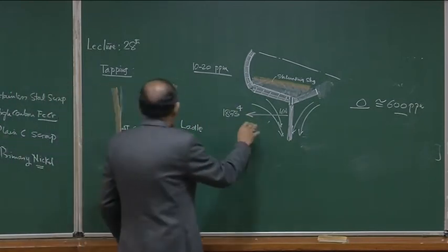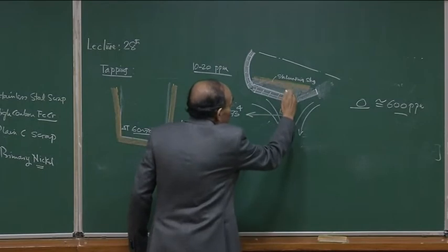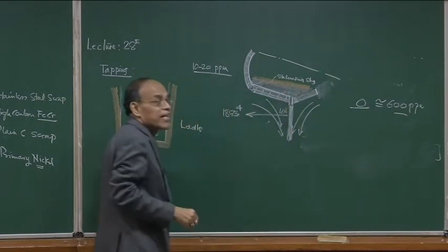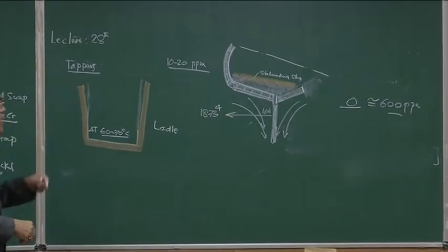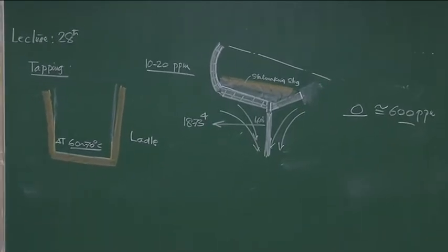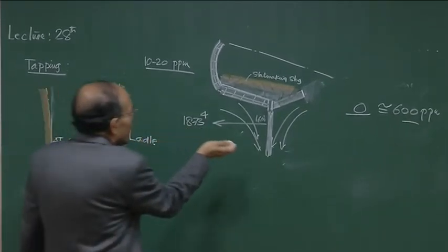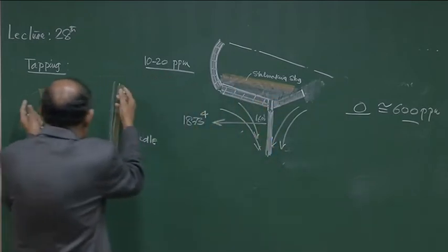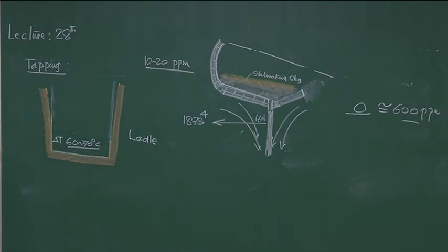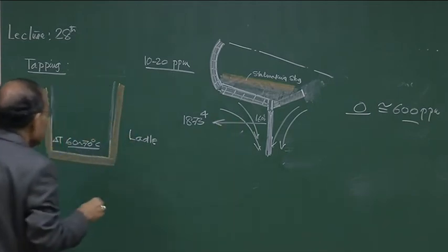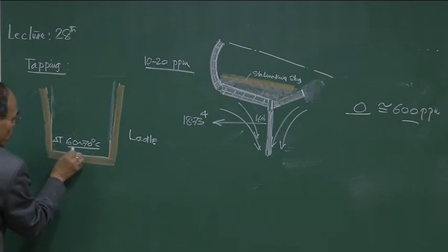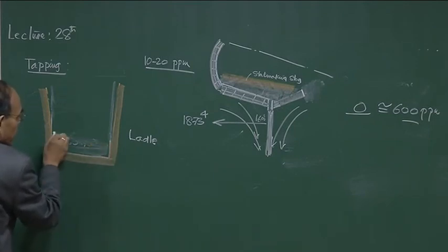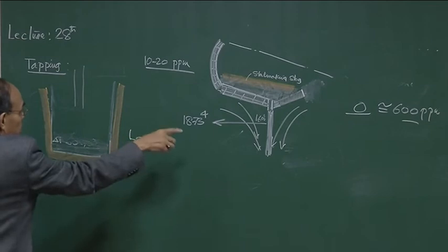So, that is why this drop is taken into account, that we want to have 1610 degrees, 1590 degrees centigrade around that time of the furnace temperature. So, it is around 1600 or plus minus 10 degrees, the tapping temperature, in order to accommodate for the temperature drop in the system. As tapping goes on, the molten metal bath here is going to be rising. So, the stream is coming from the furnace, that is the stream.